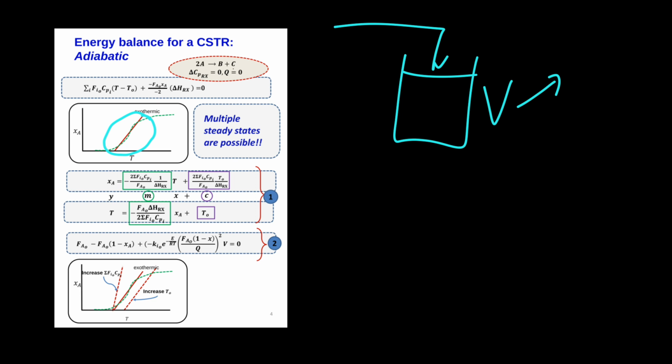So how do we rid ourselves of this multiple steady state pickle? Let's say you inherited a reactor, so the volume is already fixed, that piece of steel, it's there. You must have a certain flow, you get something from an upstream vessel, so your volumetric flow rate and your inlet stuff is fixed. So you cannot do anything about your mole balance.